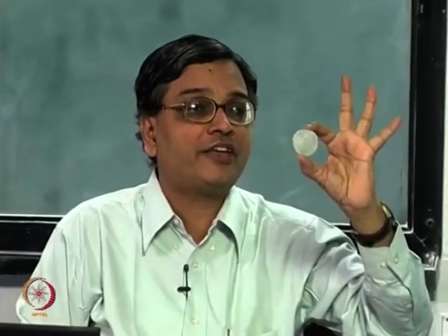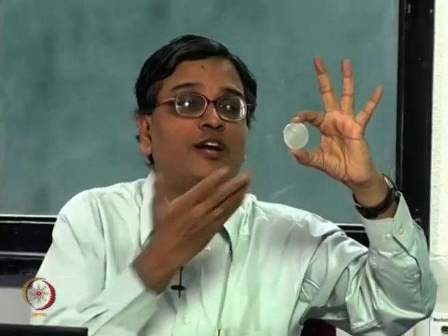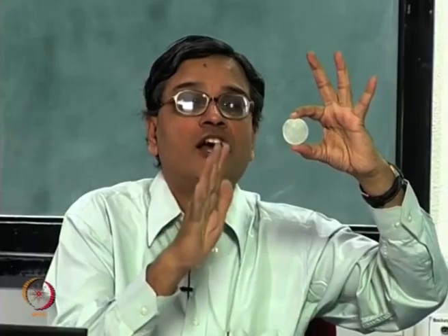And on the other hand, even if you change the geometry, I do not have a hole here, but the geometry is changed, because of the way I apply the load, plane sections do not remain plane before and after loading. So, when I move from strength of materials to theory of elasticity, I have enlarged my domain of solving problems.